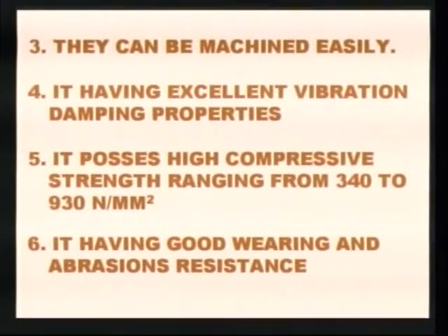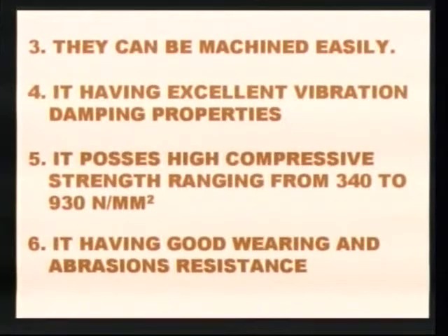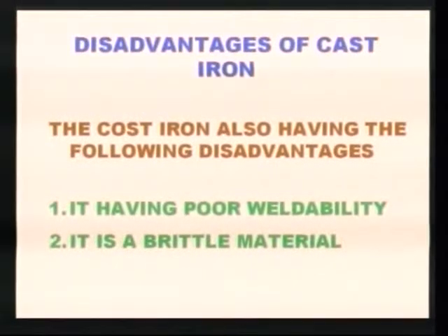Fourth, it has excellent vibration damping properties. Fifth, it possesses high compressive strength ranging from 340 to 930 Newton per mm square. Finally, the sixth advantage is it has good wear and abrasion resistance.